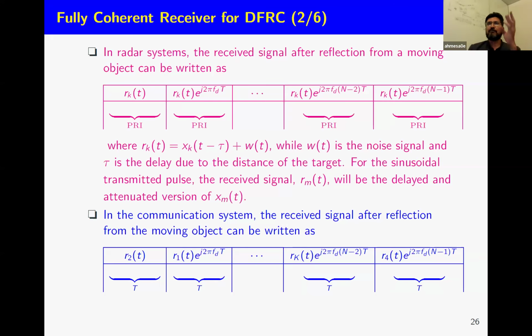Okay, so initially I'm transmitting +1, -1, +1, -1, -1, -1, +1, right? If you look at the received samples, there will be multiplicative noise. In the case of sensing, there wasn't any multiplicative noise, right? Due to that multiplicative noise, if I apply FFT, I cannot find the Doppler shift. If I cannot find the Doppler shift, I cannot find the velocity of the target, right? So this is the main difference between sensing and communication. So how can we get rid of this?